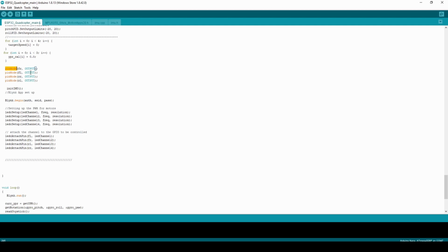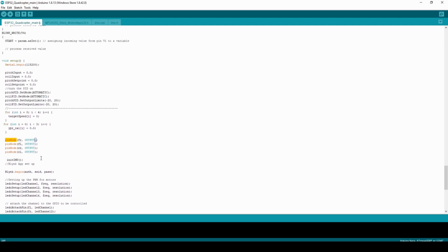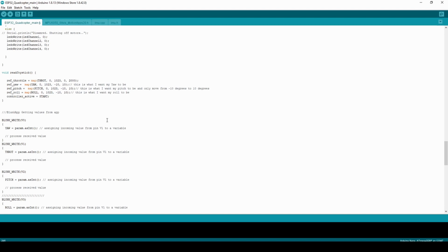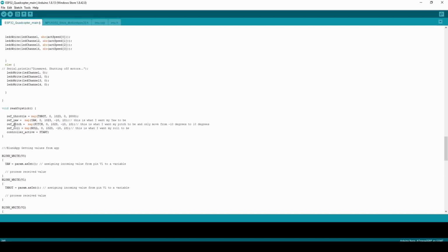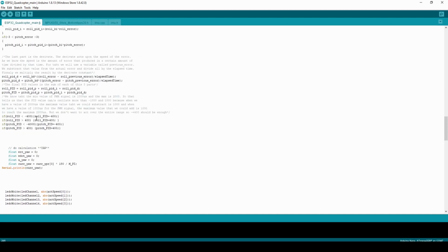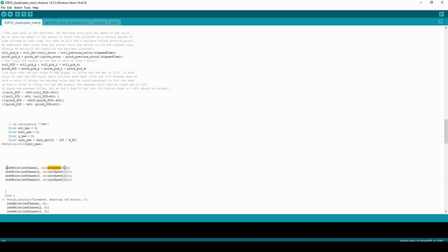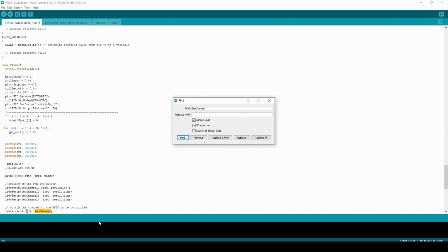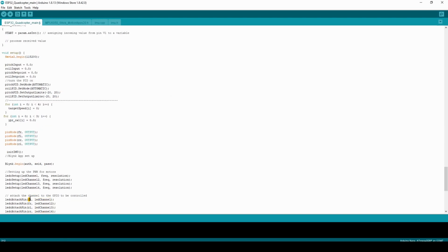As we can see here, we changed the pin mode to output. Then you're going to do some PWM signals, and your PWM signals will take your pitch and your roll and change the values of your motors' PWM signals to make it balance itself. So that is our actual speed calculation. I'll get into the PWM later, but basically I'm going to write to just channel, my speed, as easy as that. So this is my first motor, as we can see here. This is front left, so it's 12.